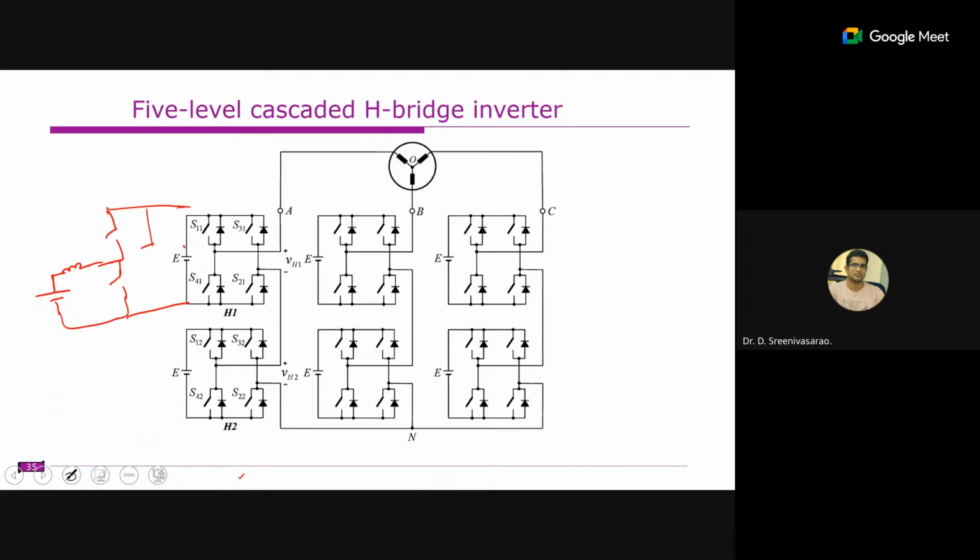And we normally have some capacitor. This is the bidirectional boost rectifier. This is one switch, and this is another switch. Depending on the mode of operation, it will be in buck mode or boost mode. Normally this voltage will be higher compared to the battery voltage, so this is the boost operation, and this is the buck operation. Likewise, it will operate. This is one more circuit. Or sometimes we use another circuit, if you require some isolation. In that case, we may prefer the dual active bridge converters.